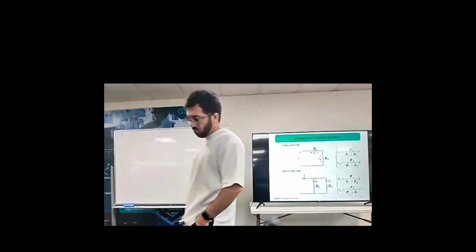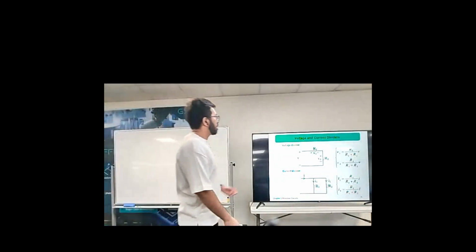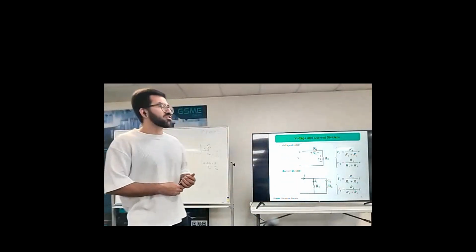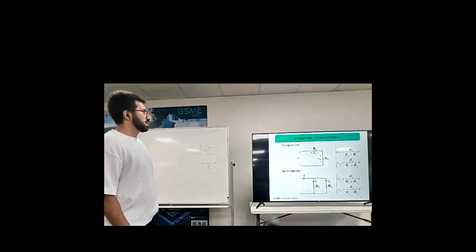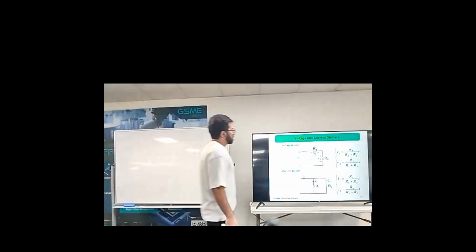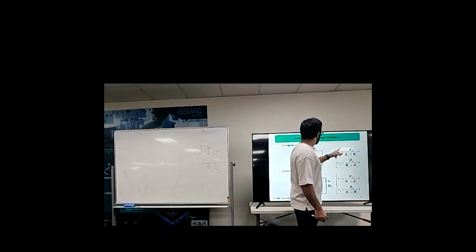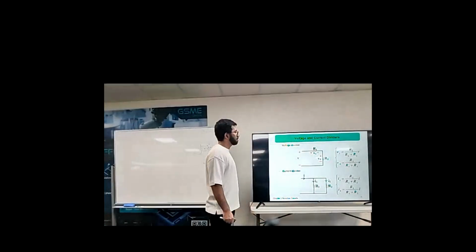We have two most commonly used circuits here, voltage divider and current divider. If you have two resistors in series, the voltage across each of them is proportional to its value over the sum of the resistors. That means if I have two resistors in series, which one of them is much bigger than the other one, I can easily omit the smaller one.